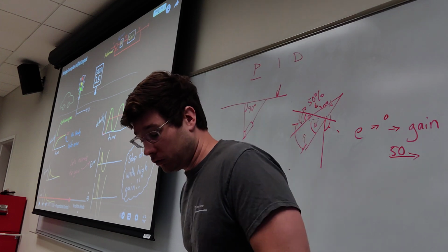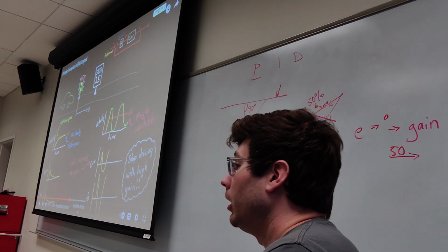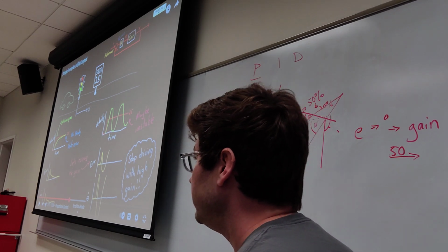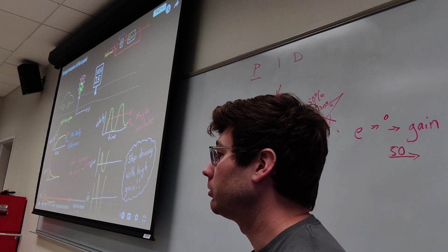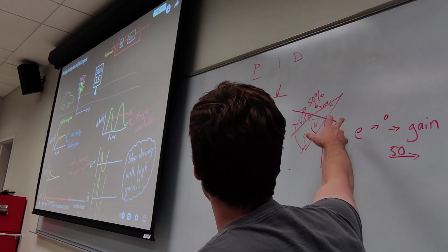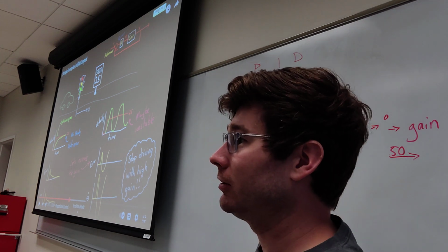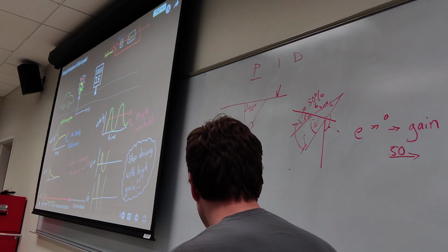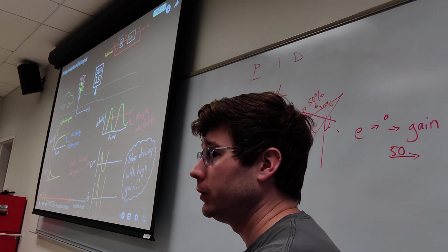So we can actually make this in structured text. Again, each of these systems, P, I, and D, can be implemented in just a couple lines of code, where it's literally the angle we are, minus the angle we should be at, times our gain factor, for example. That would be the simple proportional case. And we're going to go over the integral and derivative here.